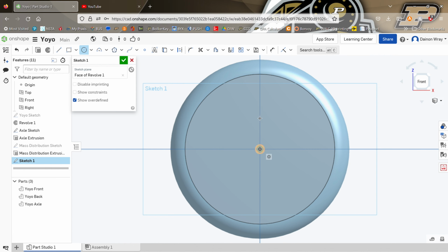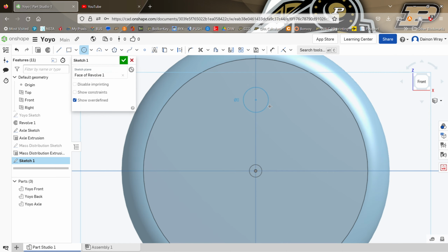That's okay. I know how to constrain it to be vertical. So once I have that circle, I'm going to select it. That looks like an amazing size, 0.251. I'm going to dimension it by pressing D on my keypad or selecting up here. I'm going to click on the circle, drag out, and I'll round it up to the hundredths place, 0.25 or quarter of an inch diameter.